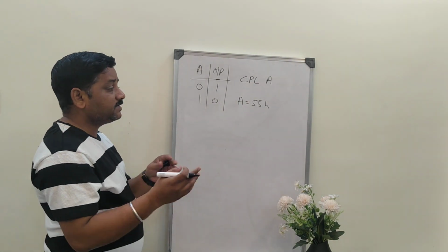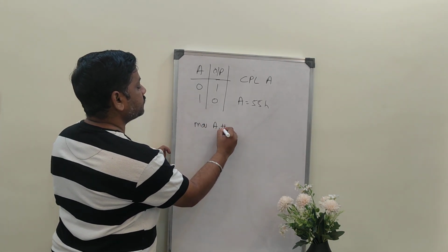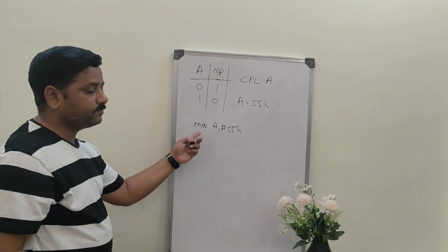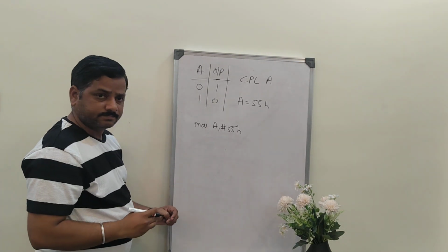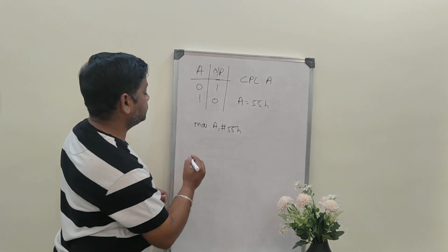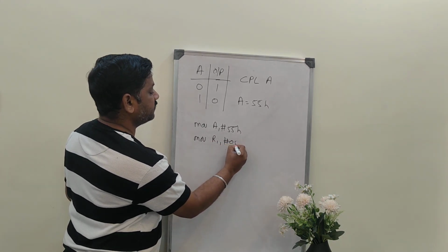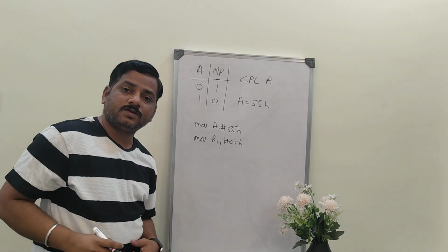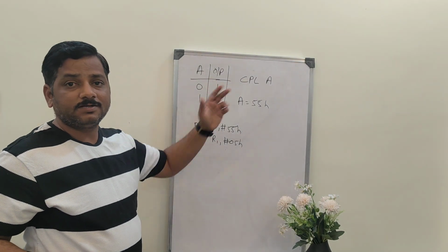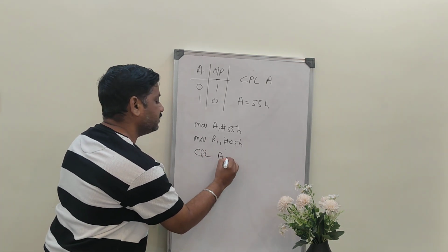So first I will take some input to accumulator. MOV A, you write whatever the input you want, because in the question they have not mentioned what the input is. You just give the input to accumulator and then 5 times you have to repeat it. So you give that count 5 to one register, MOV R1, #05H. Give it to register R1 and then you write what you want to do. You want to complement it, you need to toggle it, right? So I will write CPL A.